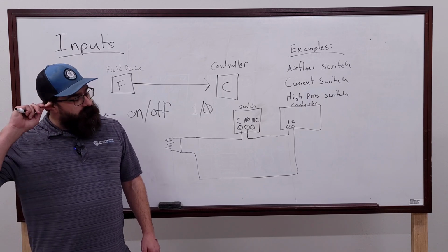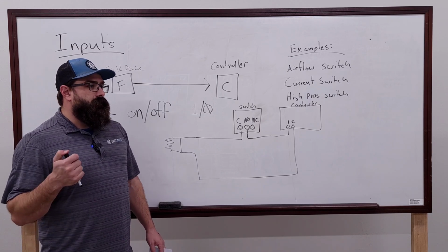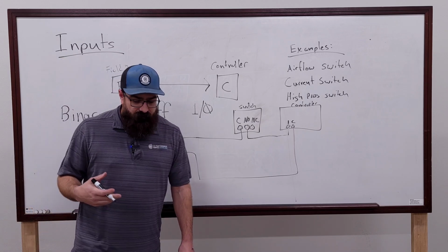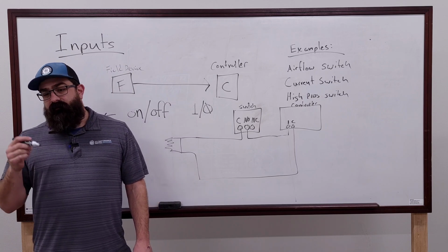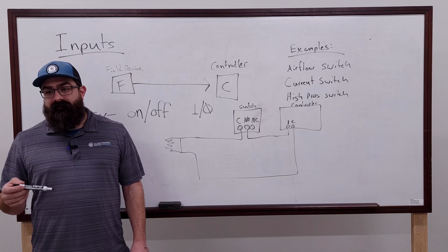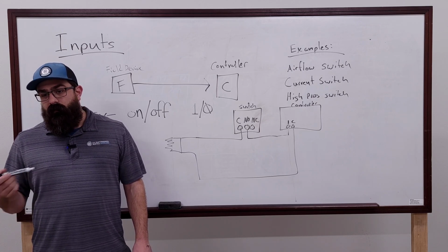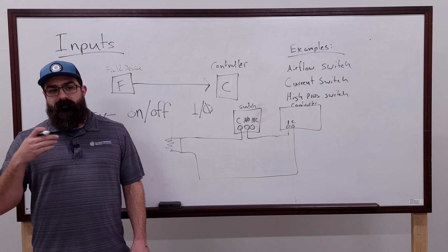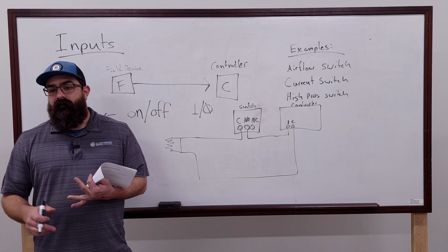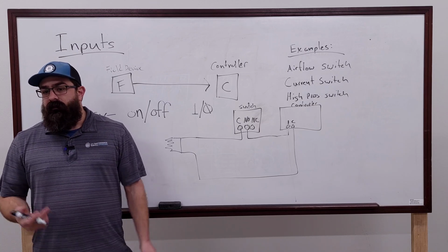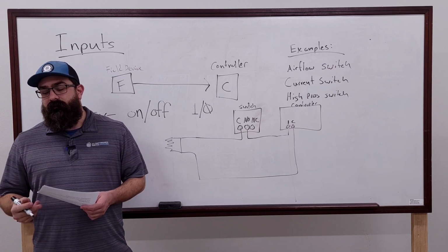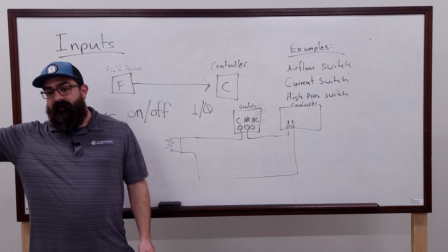So like Honeywell and Distech, I'll just stick to those because that's what we do the majority of, actually have universal inputs, and those universal inputs can be configured as a dry contact, or you can use them for monitoring a thermistor, a transducer with a 0 to 10 or 2 to 10 or 4 to 20, or they can monitor just a contact closure because they can source their own voltage from the controller to send something out and bring back.